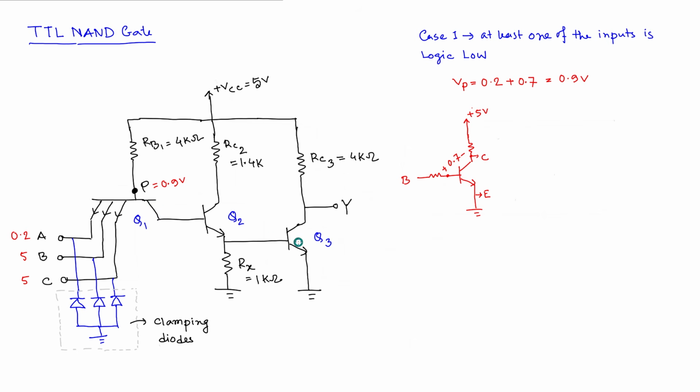And we are going to take the same assumption here whenever we say that if the path from here to here to here, or if the whole path needs to be turned on, or if current can flow through that path, this particular junction needs to be forward biased, and the voltage required will be 0.7, not 0.5. So again, I will request you to investigate why is that.